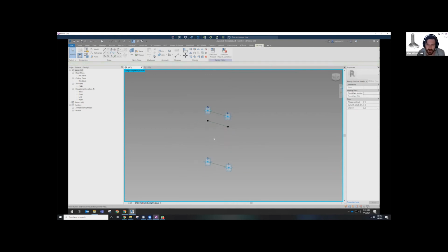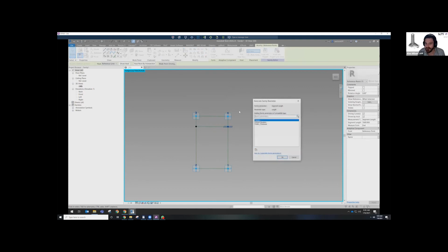At that point, I'm going to hide those. I need to create a chain around the outside. I then draw my lines in here and here. At that point, I can select a chain. I can click create form, and it's exactly the same as the first example. It creates the forms. I can create the offset. I can parameterize all of this if I want to as well. So if I wanted to create a parameter for the offset of here, I could select this and just assign a parameter. The second example is, instead of using a segment length, to use a curve normal length.